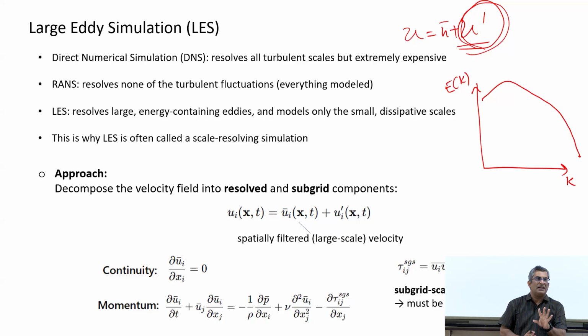But please remember that you model the turbulent stress terms, but in RANS what you get is the mean quantities only. We don't have information on the turbulence quantity. Yes, according to the model that you use, you have these terms.